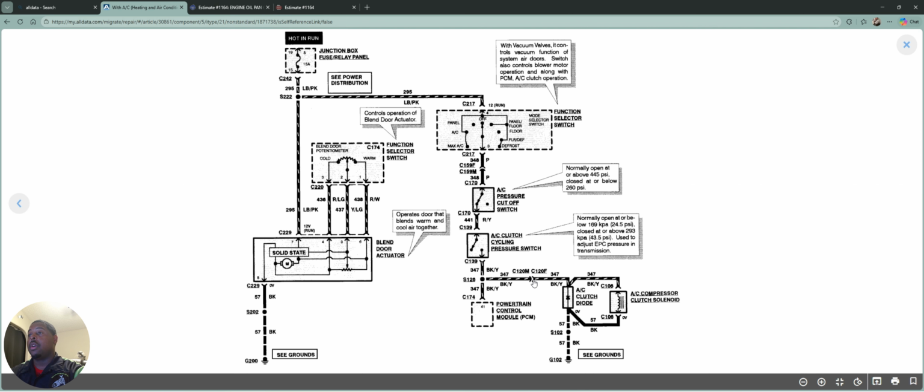Now, if you don't get 12 volts, and I think in your post, if I remember correctly, I put leads to the compressor AC clutch connector reading 0.014 volts, and from the low pressure switch harness shows 12 volts.